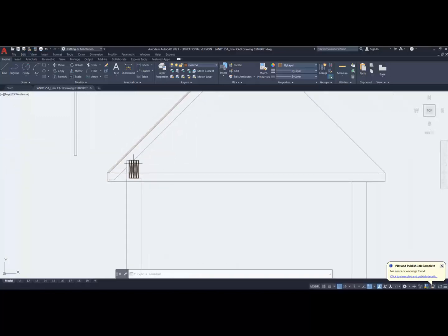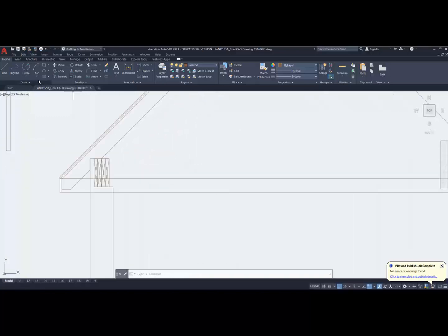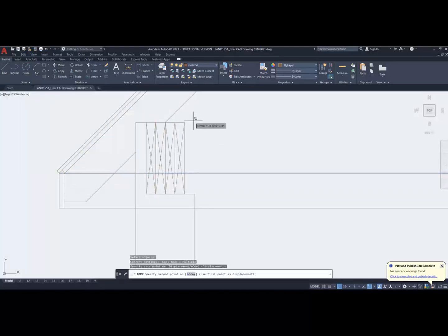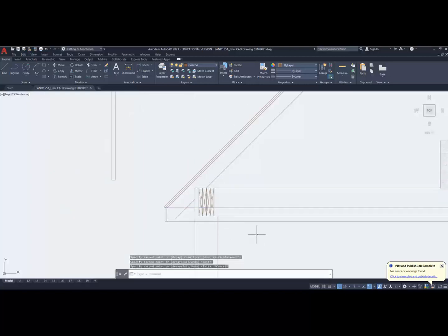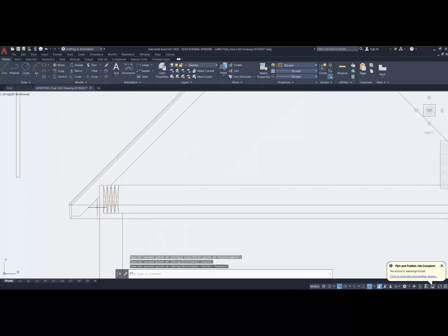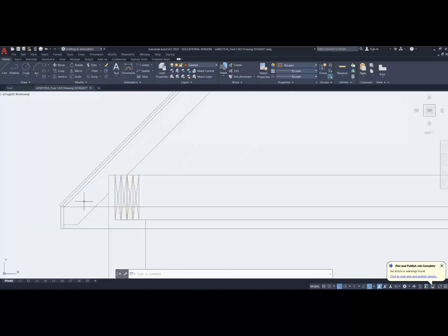I'm not going to see anything past the edge of this beam. In fact, this beam I'm going to see this entire length. So I'm going to do a couple things first. I'm going to copy a line rather than draw them. Copy this line. That's the back side of the beam. There's the lip of the edge of the beam. Nothing behind that am I going to be able to see. This is the fascia board. That's this board here. And along the back, all I'm going to see is a very short section of the fascia board. So I won't see it back there. I'm going to see it between these two.